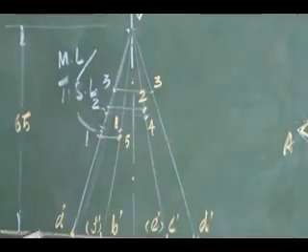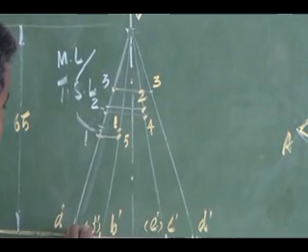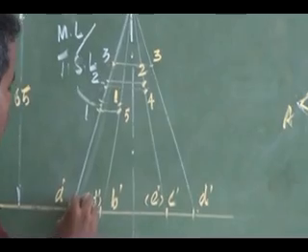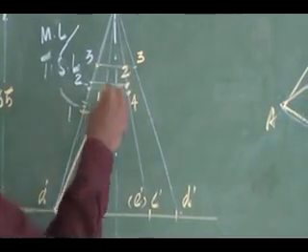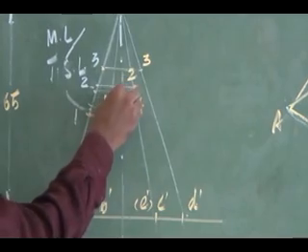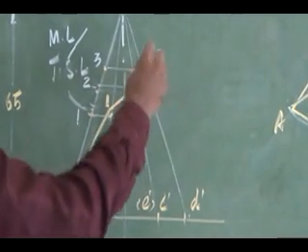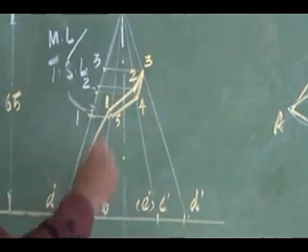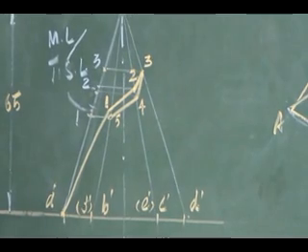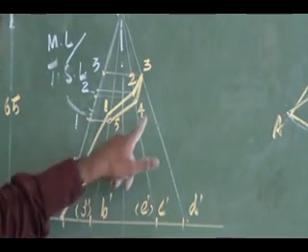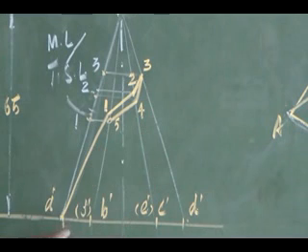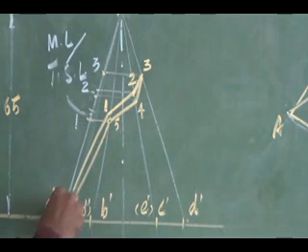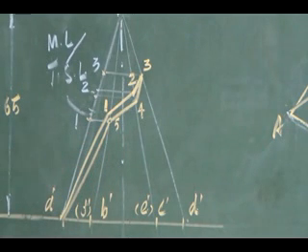Now you connect these cutting points in the front view. Okay. From A, the thread is bound from the base corner A. So A to 1. Then 1 to 2. Then 2 to 3. Then 3 to 4. 4 to 5. Then again it is coming here. See here. This cutting point 4 falls on E and F. So 5 to 6. Is it the right representation in my front view?